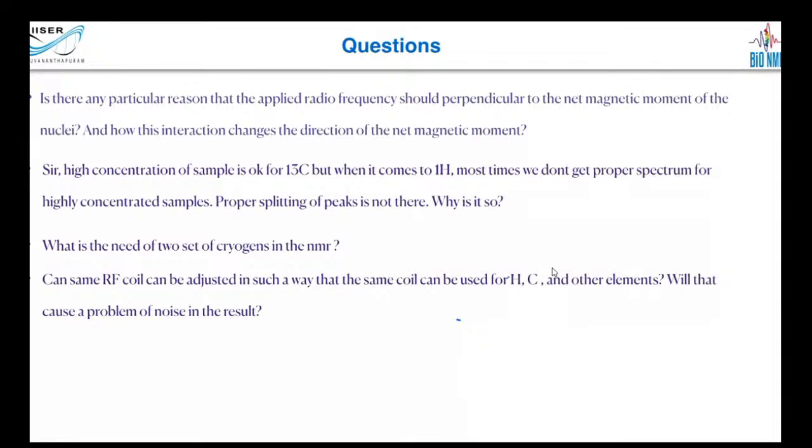Now the problem with capacitance is that you cannot have a really huge capacitor that will be able to have a frequency. What we are doing in the probe, as well as in our radio, is that when you are tuning this knob, you are basically adjusting the capacitance such that the tuning frequency of that LC circuit matches the frequency from the airwaves, right? This is what we are doing when we are tuning a radio. The same thing is what is happening in NMR also.